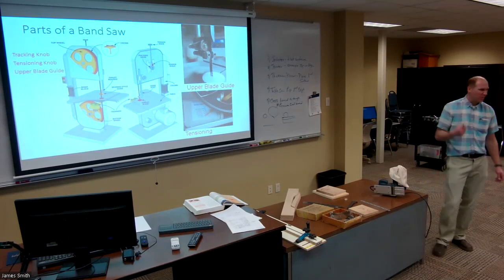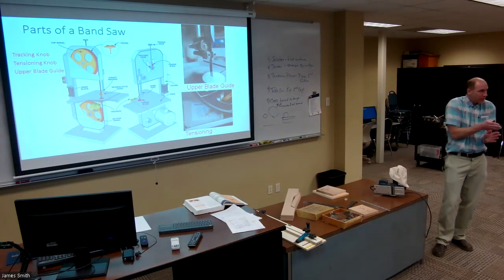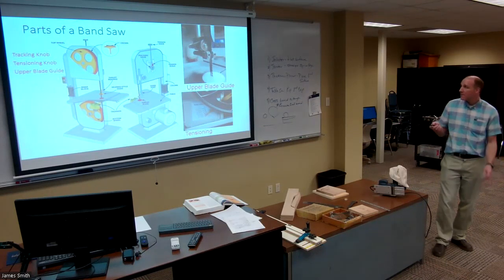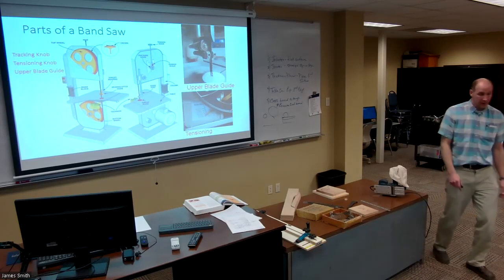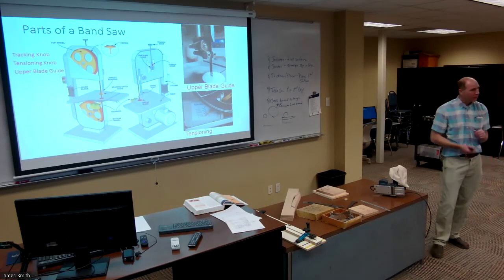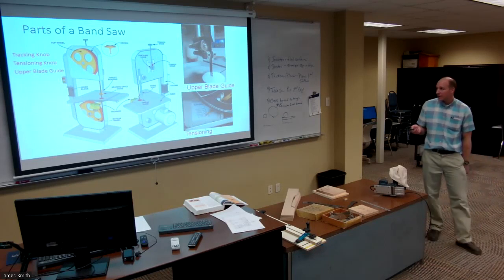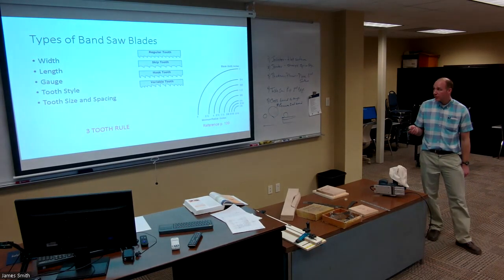The other thing is, we don't really change our blades very much, because when you change out a blade, you have to change everything. You have to change the position of your blade guide, and you have to change the adjustments of your little side supports, your bushings. So we typically just run a 1/4 inch blade, and you can cut really sharp curves, and it's pretty great that way. We do resawing operations with it too. Again, it's not optimal, but we do it, and you get pretty good results.